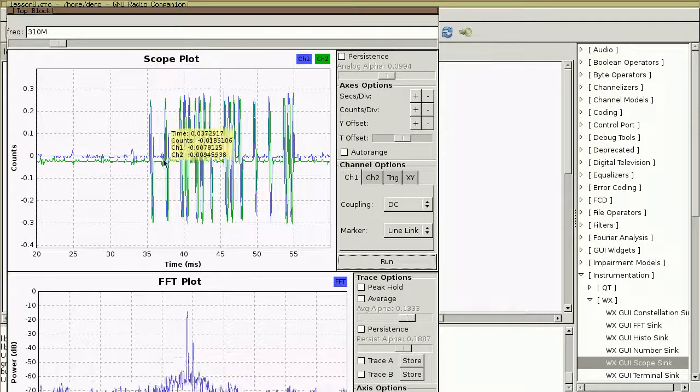And if you look closely, you can see the difference between the burst and this stuff around 0. This is a short burst, and then a short, and then a long, and there's a little bit of 0 there, and then another long. So it's short, short, long, long, short, long, short, short, short, long. And one of the things I notice about this pattern is that it is the same pattern that I have the dip switches set to in the garage door opener remote.